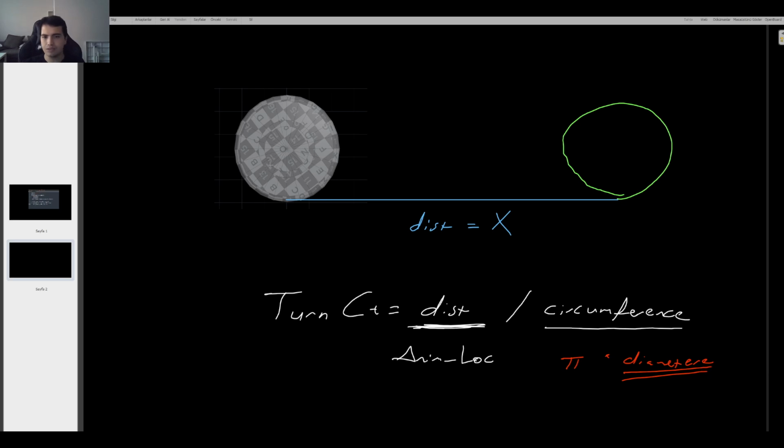As we are dealing in a circular manner and we don't have any additional data, the top point of y of my bounding box and the bottom point of it, the difference between these, gives my diameter. And we have single expressions for that. The top point is represented with $ymax, and the bottom point is $ymin. And the difference between them is my diameter.